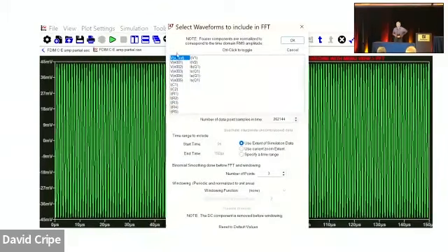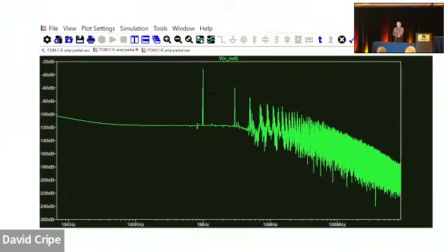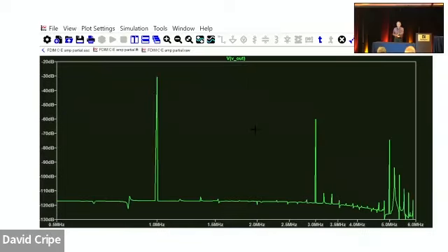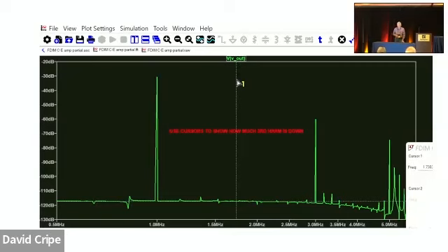Now the FFT, that's on the View menu. It says FFT. Then it asks me which parameter I want to plot, but it highlights the one I'm currently looking at. So I say, do that one. It creates a separate plot pane, and it's really huge. So I zoom in. I see my fundamental, my third harmonic, and my fifth harmonic. I think the second doesn't amount to anything, so you don't really see it.